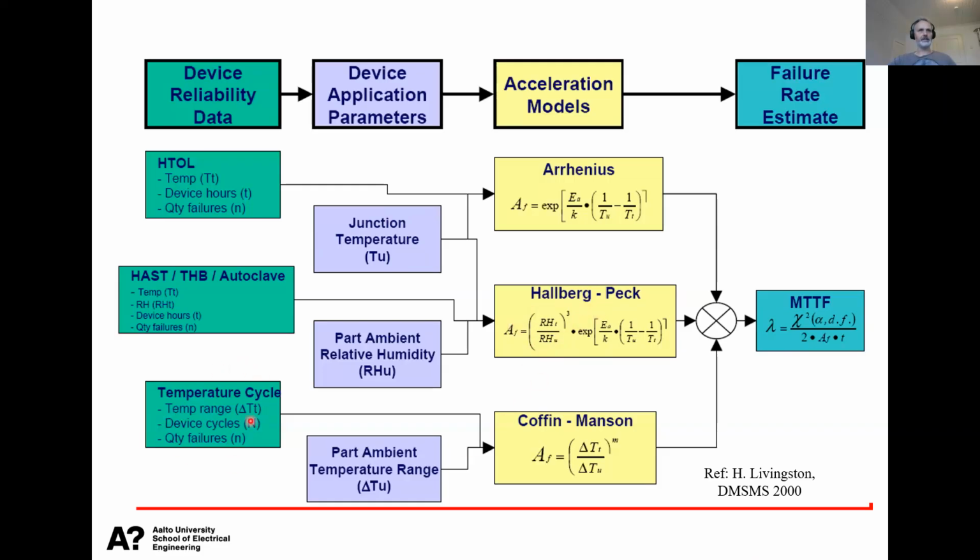For temperature cycling, we have the classical Coffin-Manson equation for fatigue failure. This has developed from mechanical engineering, from rotating axles and cyclic bending. This kind of model has been used for maybe even close to 100 years already, at least several decades. So these models are quite simple.